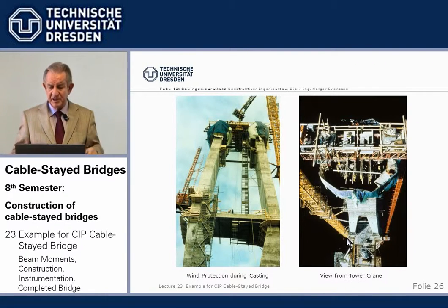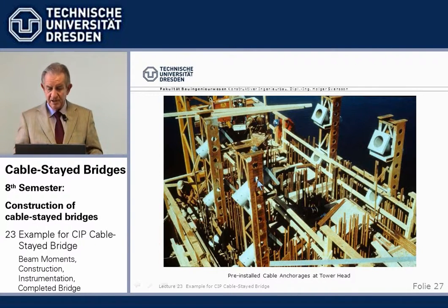So what we did is we proposed, and the contractor built, steel frames from channels in this instance, where the steel pipes were rigidly welded. And these frames were put section-wise one on top of the other, and the reinforcement was installed around.